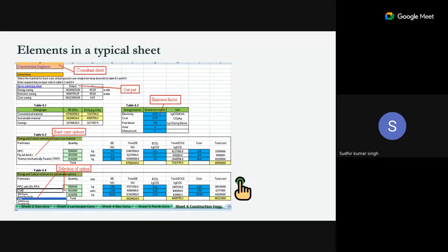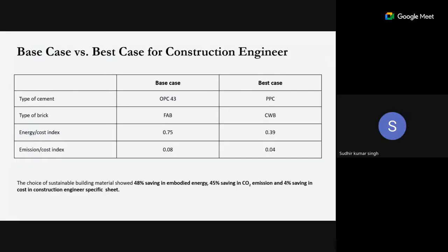use for decision making in a certain building. So we have to decide what is the major impact making material that only we are going to take into the decision making, right? So there are major impact making materials, say cement, blocks and steel. If we select and the best case we select, then we go into the decision making. So these are the results. Once the result is there, if I'm selecting a certain material, I have to see what effect it is going to put on the cost of that particular project.